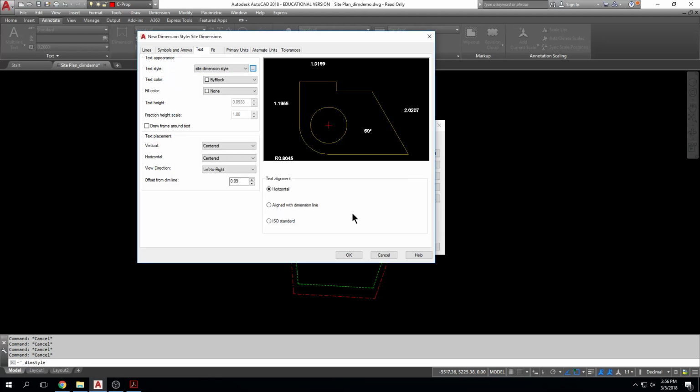That's good. All right, so I'm on page 1-103 now, right? And I look here and everything looks pretty good. This is going to be above, and this is in the book. This is going to be centered left to right here. And instead of horizontal, I want this aligned with dimension line, right? So if I dimension this object, I want this to be parallel with it, okay? So I've done all those things, look good.